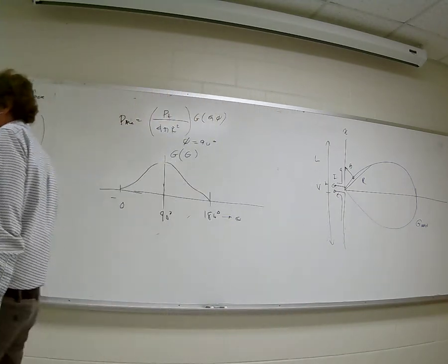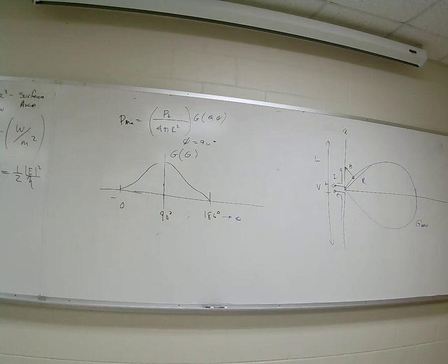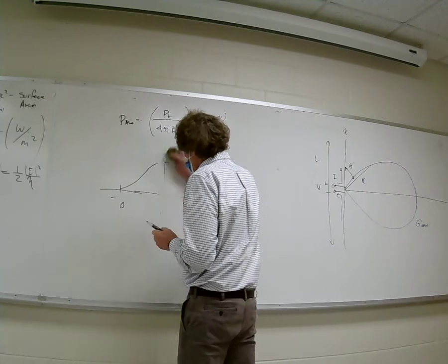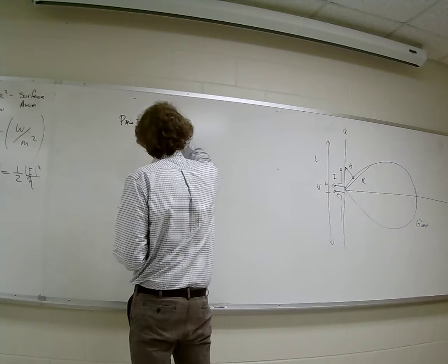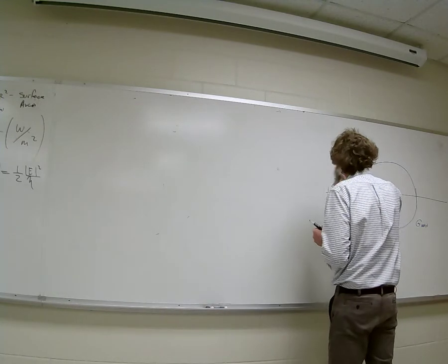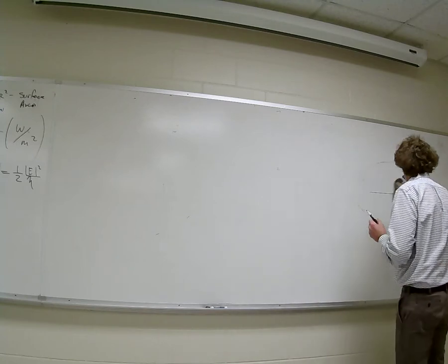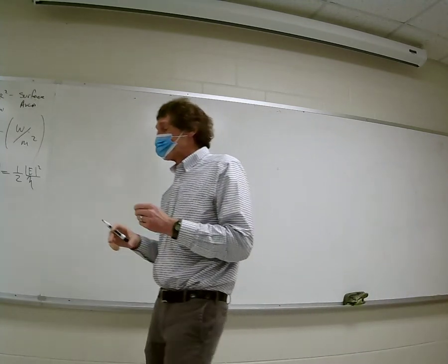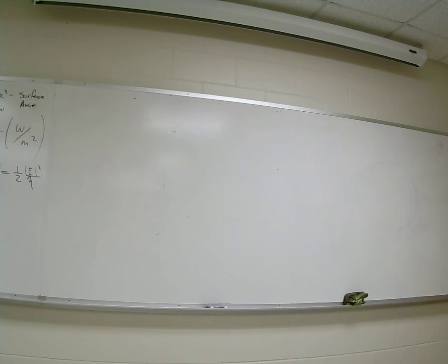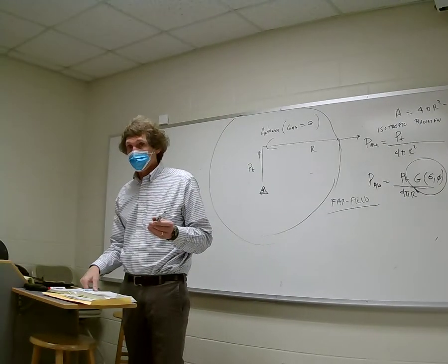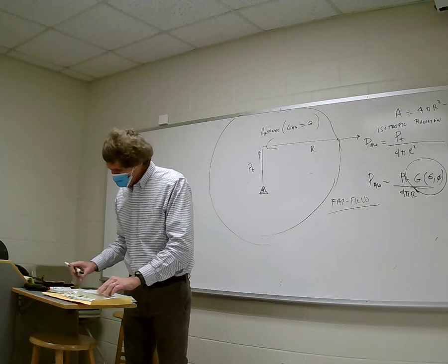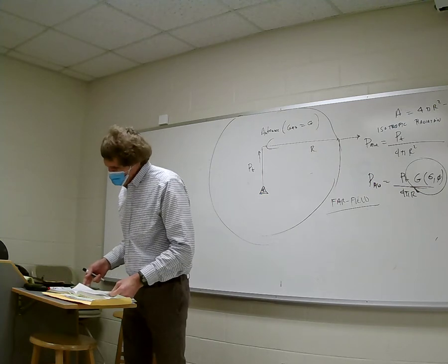Now, when we talk about gain, one of the things you have to do is also appreciate what it really means to you and me. I try to give you an idea of that. But there's a few things that happen that are necessary outcomes. And the question that should be in mind, well, how do I calculate it for an antenna, right? And the way you have to do that is you have to find the electric field from that antenna as a function of angle. And then from there you get the power. Once you have the power, then you can get the gain. I'm going to show you how, okay? And I'm not trying to bore you with this, but I can imagine you want to see some hardcore work.